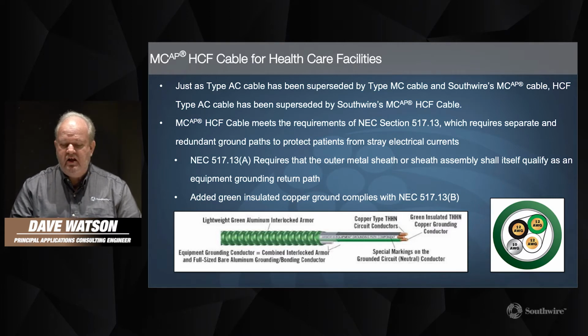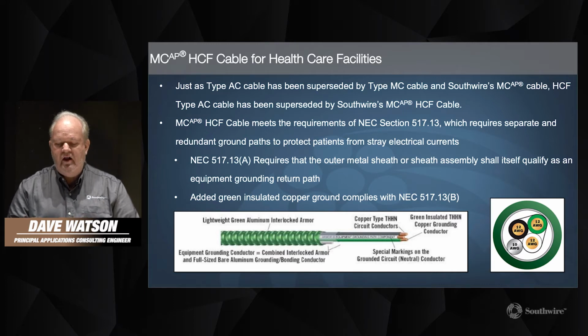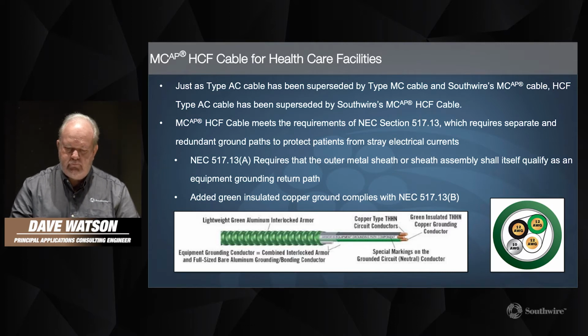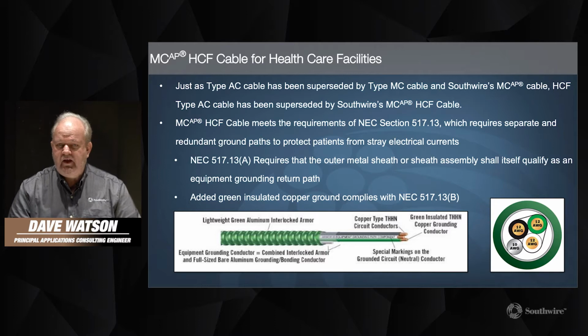In addition, this product also has an added green insulated copper equipment grounding conductor. So a redundant grounding conductor. That's going to comply with NEC 517.13b. And now let's take a look at that product.